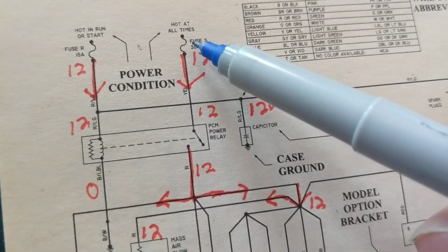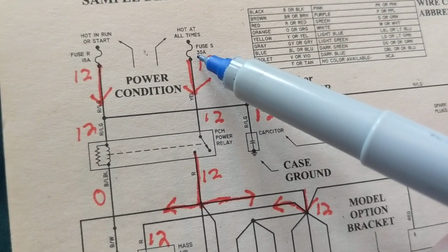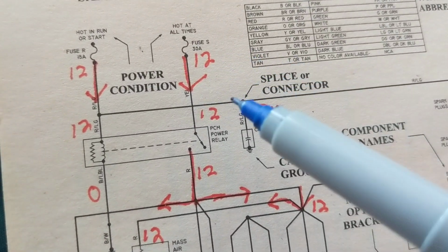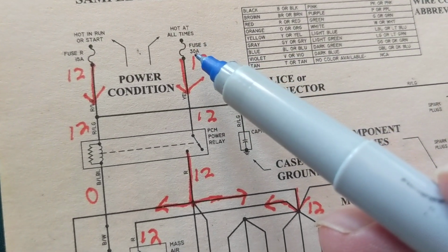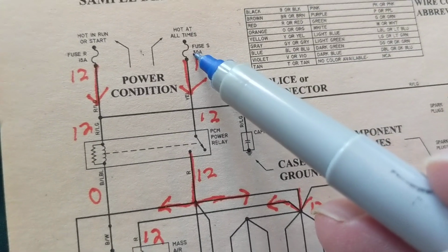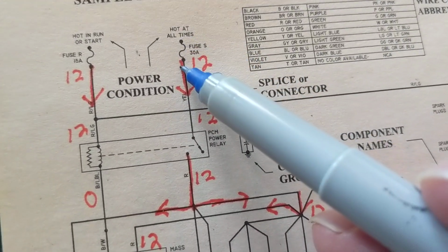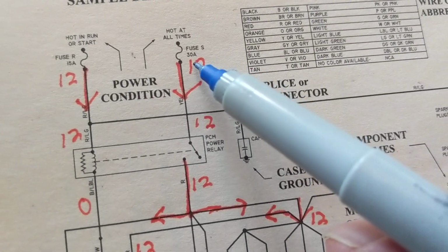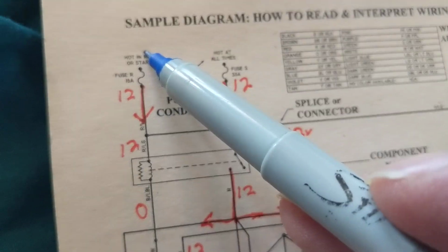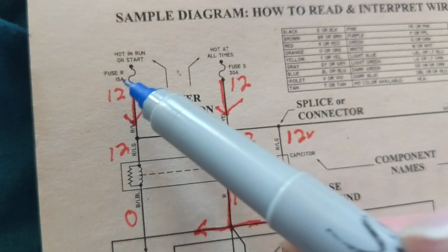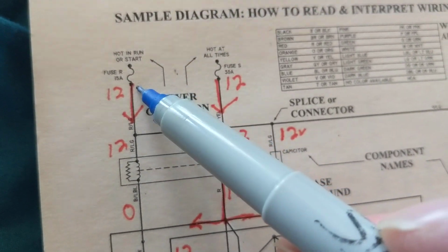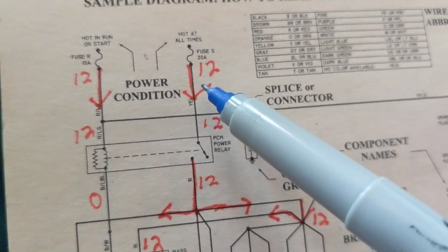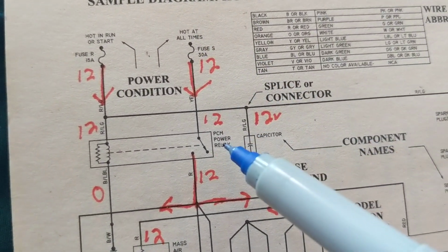This conductor has 0 ohms, very close to 0 ohms. Oh, how do I get that? Ohm's law. I don't want to get too deep. Ohm's law tells us if there's 0 ohms or close to it, you could have a 0 volt drop across that component. Therefore, if there's 12 volts here, 12 volts over here across a 30 amp. If there's 12 volts here, 12 over here across a 15 amp, a 10 amp, a 5 amp, a 2 amp, doesn't matter. Ohm's law gives us the right to analyze it that way.